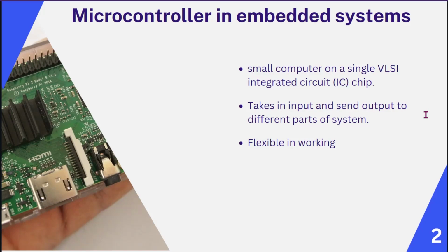One of the key features of these controllers is their ability to interface with other electronic devices. Microcontrollers can communicate with other devices through a variety of communication protocols such as UART, SPI, and I2C. They can also be programmed to respond to various types of inputs, including sensors, switches, and buttons. They also need to be highly reliable and are designed to perform specific tasks that they are optimized for, with reliability and long-term operation. This is critical in applications where failure is not acceptable, especially in devices such as medical and aerospace systems. Finally, microcontrollers are also relatively inexpensive compared to general purpose computers.